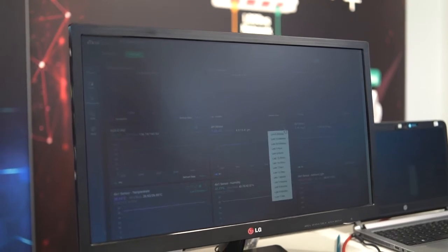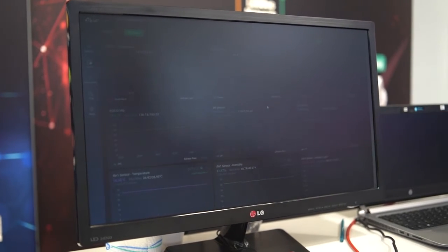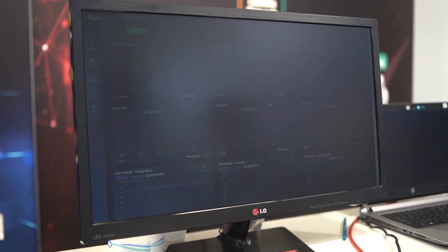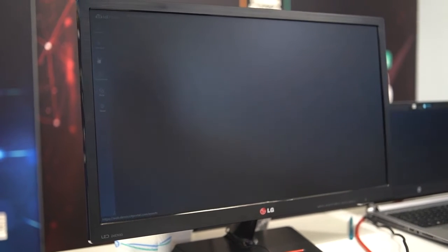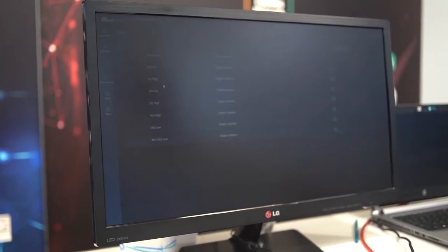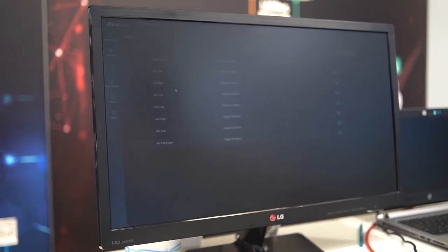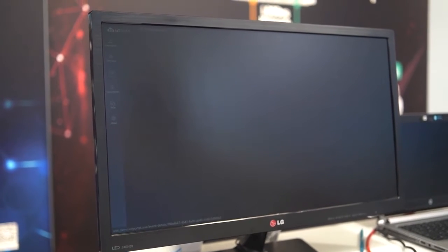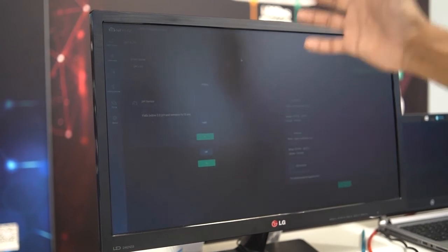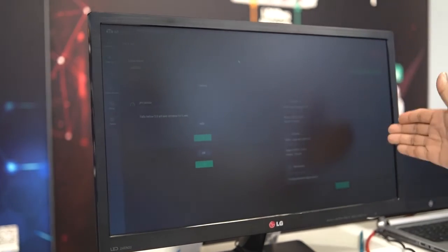And similarly, drawing attention to the pH sensor, we have pH values that can be monitored, and these fluctuations can then be recorded and acted upon. What I have done here is set up an event, and we have an event manager which can monitor any of these conditions and then take action. So for the pH, when the pH level drops below a threshold, here we have the event, the condition for the event, and then the action for the event.